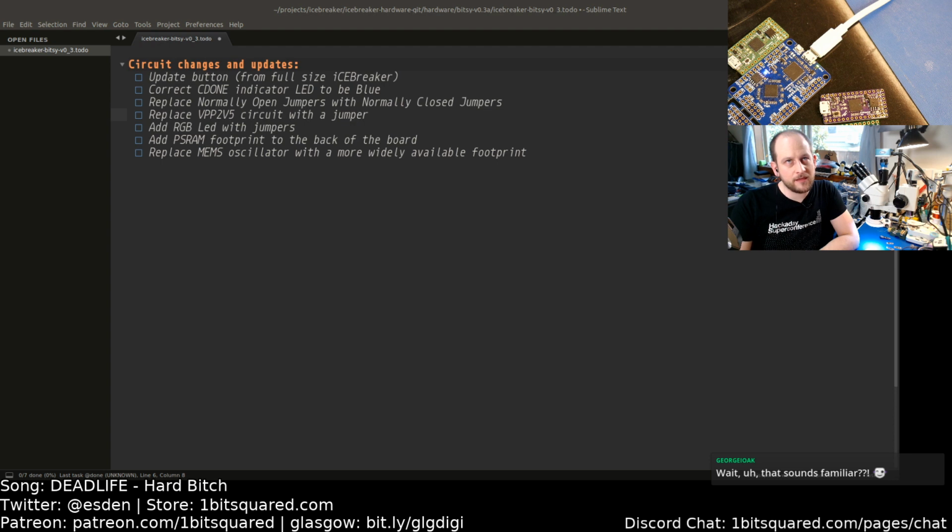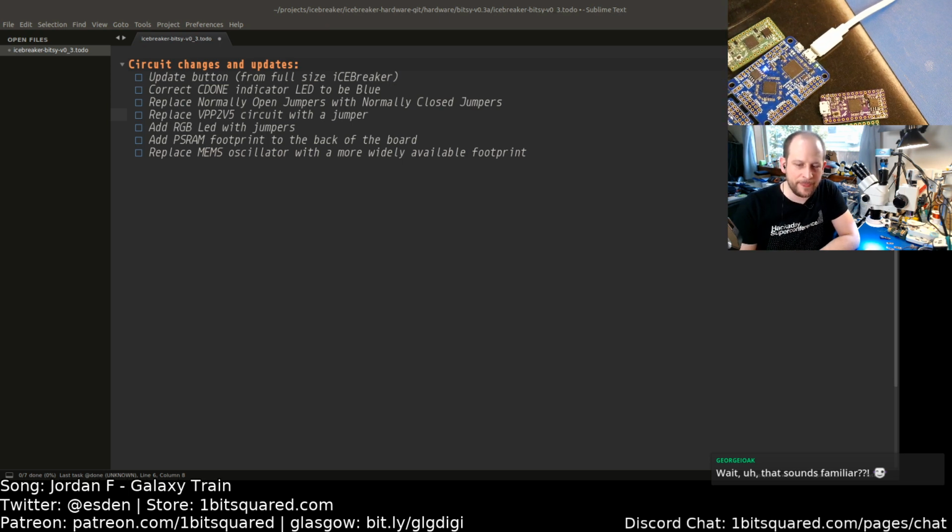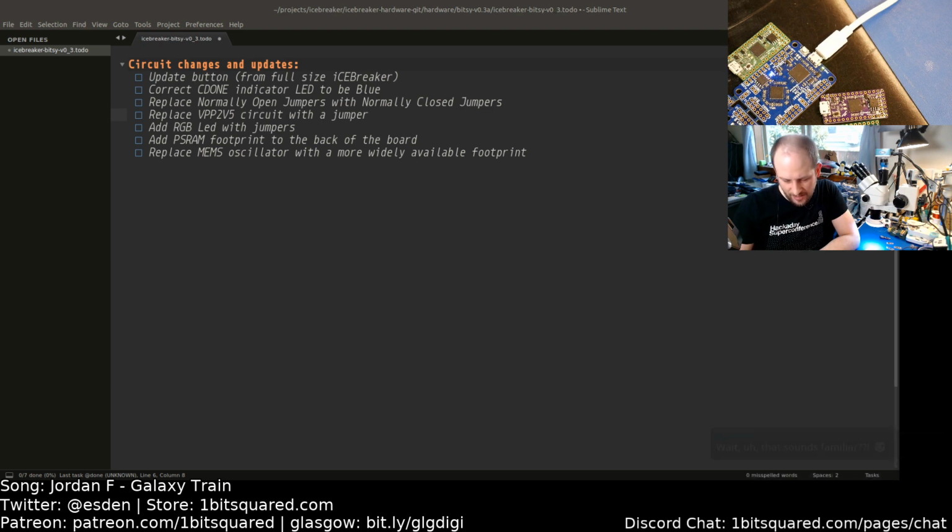I currently still use the micro USB connectors, and I had a very good experience with those. Sorry, I might switch to USB-C eventually. I have in my cart from LCSC a few parts that are just the standard USB 2.0 USB-C connectors. So there are two types of USB-C connector footprints. One is the one that everyone thinks about, the USB 3.0.